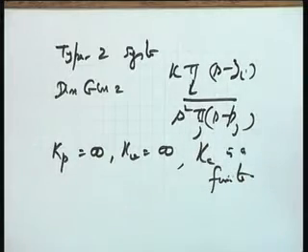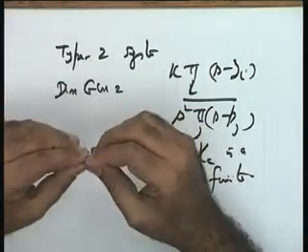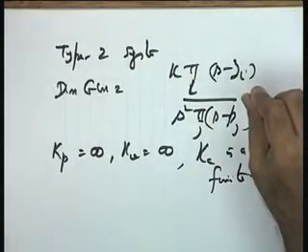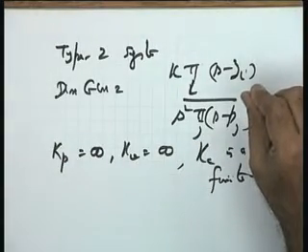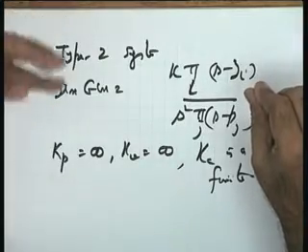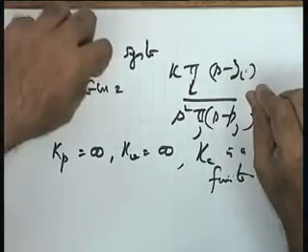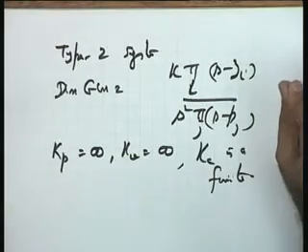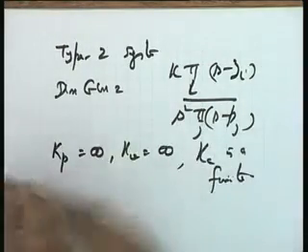If the user has not specified anything else, in that particular case, can I make a statement that if the system has an integrator inbuilt into it, you may like to go for a position or a PD controller. But if the system has not an integrator inbuilt into it, you may like to settle for a PI controller. Is this statement okay, please?